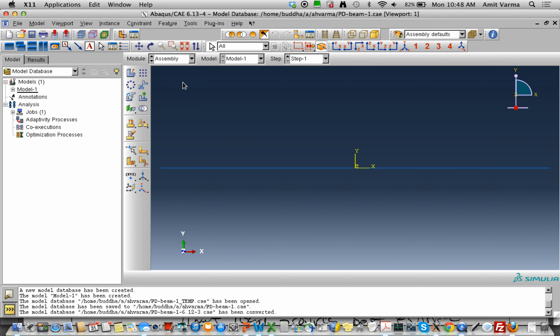After that, you get to the assembly. This is pretty straightforward. You don't have to do anything. It just shows up. It's the only beam element that's there. Now, one thing that you need to do here is introduce the node associated with applying the force. So you can do that using the partition edge tool. You all used it last time when you did your exam number 1.